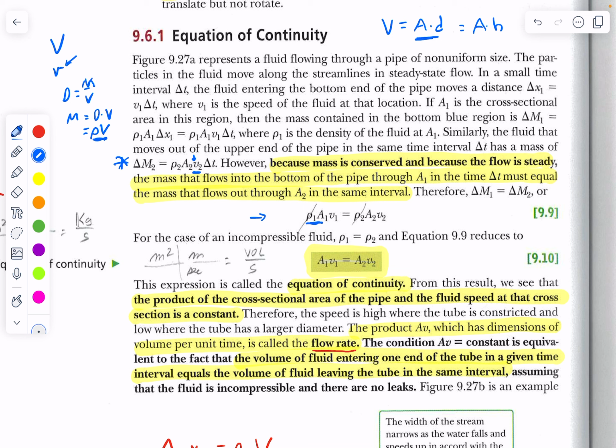And if you remember that density is mass per volume, and you're multiplying by area, you're going to have your mass per some distance or length represented there. And then we're multiplying by the velocity, and the velocity is a distance or length per period of time. And so when everything cancels, you see that the mass of your water per time that is entering a hose or a pipe or reaching a certain point in the river has to equal the mass per period of time that exits.